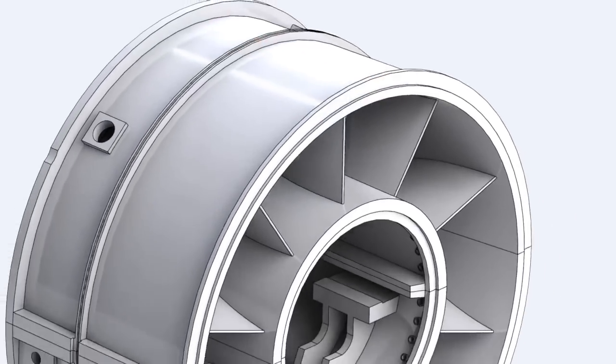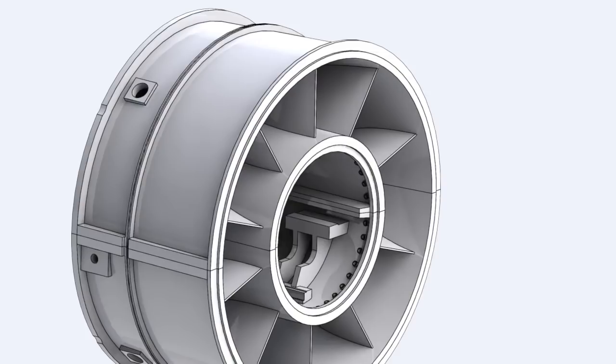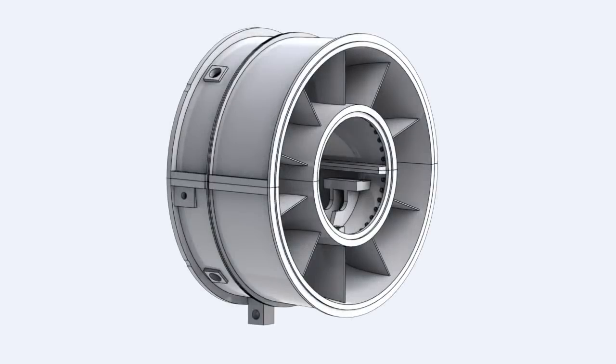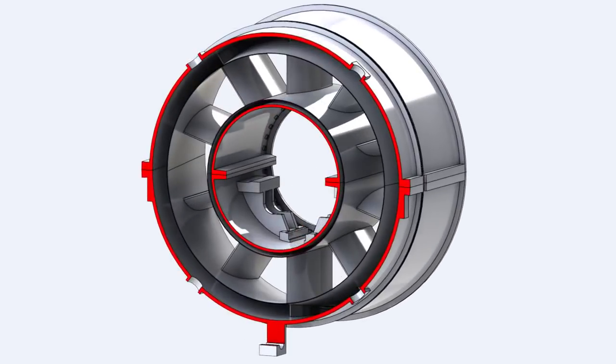The inner and outer diffuser and the airfoil-shaped fairing surfaces are metal surfaces which protect the exhaust frame parts from being exposed to the high temperatures of exhaust gases to maintain temperature stability. This stability is required to keep the exhaust frame inner cylinder, which carries the bearing number 3, in the accurate position, avoiding any misalignment. To ensure the temperature stability, air is forced by means of 2 off-base blowers between the exhaust frame outer cylinder and the exhaust frame diffuser surface through 4 ports.